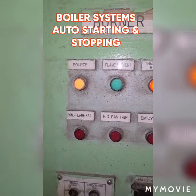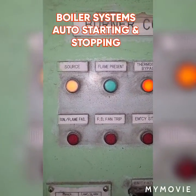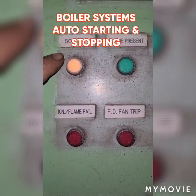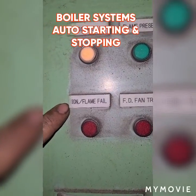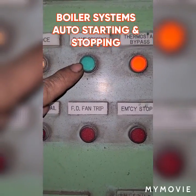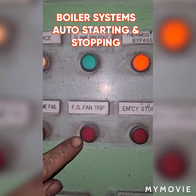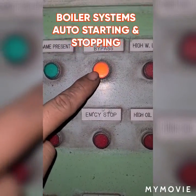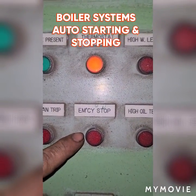Okay guys, this is my boiler control panel. As you can see here, there is my source indicator light. This is a yellow light, and I have the red indicator light for ignition flame failure. This green light is the flame reset indication. The red one is the forced draft fan trip, and this is a thermostat bypass. This is the orange light. This is the emergency light.